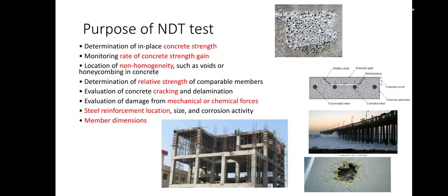What are the purposes of NDT tests? Mainly we can find the in-place compressive strength, and second we can monitor the rate of concrete strength gain. Suppose you are making a concrete: at the first day what is the strength, at the third day, at the seventh day, at the 28th day?